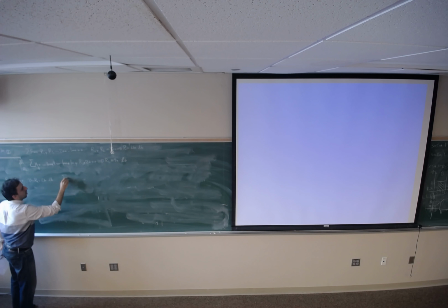R1 goes up, minus V goes down, equals 0. There is no other force on the section that I cut. So V would be R1, and R1 is 210 pounds. For the moment, R1 doesn't have any moment at this point because the distance is 0.